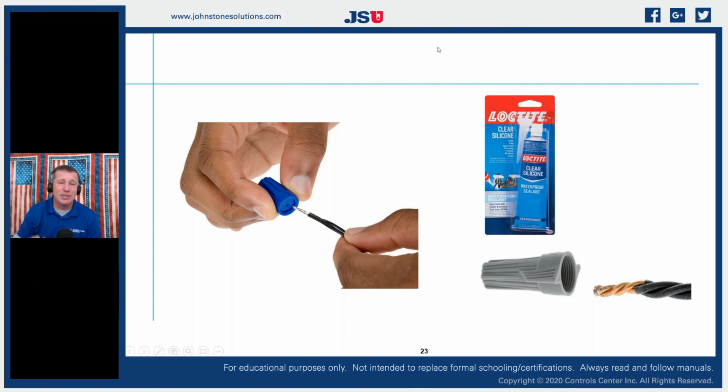And that's something we've never talked about before when we're working with legacy wiring in general. If I needed to extend an 18/8 thermostat wire, I simply got another piece of 18/8, twisted them together, put some wire nuts on them, and off I went, and I never had any problems. If I use that exact same piece of wire on a new communicating system, I'm probably going to have problems. So in our technical support side of Johnstone, what we have been finding with new installations of communicating systems is that our number one culprit is wiring,